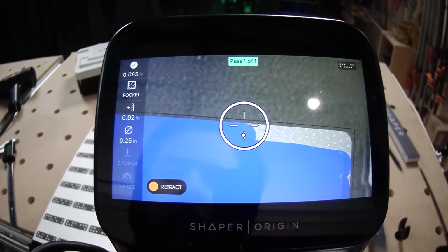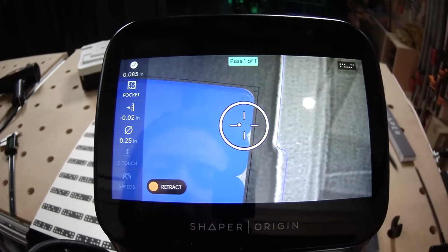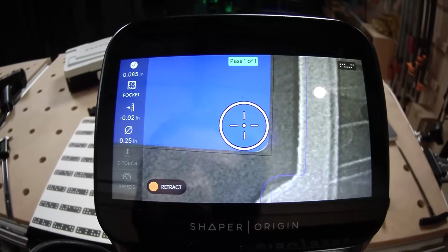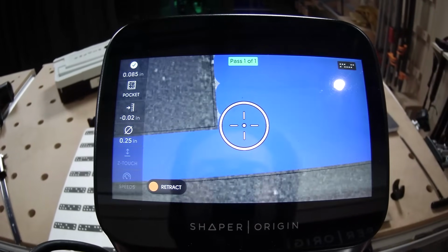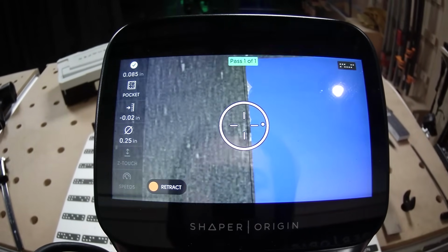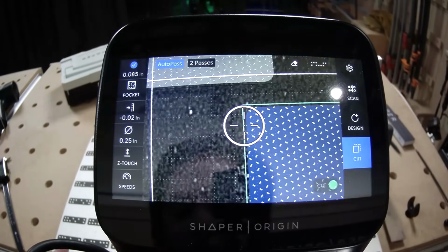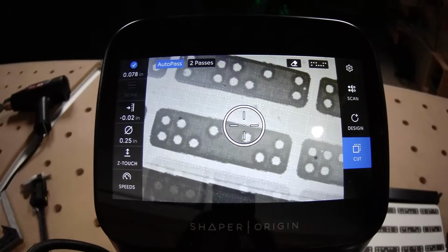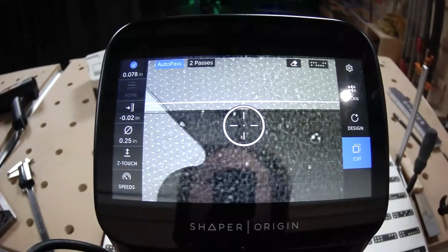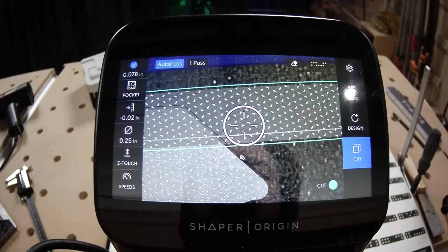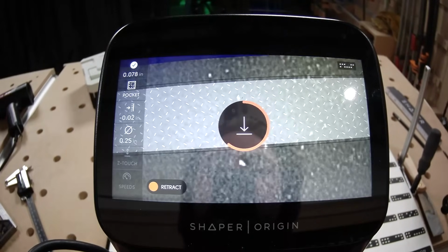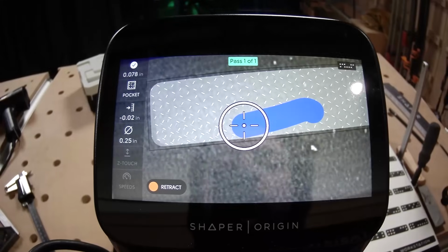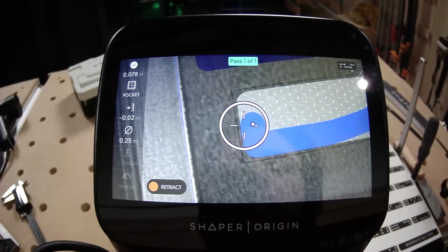That's when you get nasty foam residue stuck to your router bit, which is a negative reinforcement loop there. More stuff stuck to the router bit just creates more and more friction and more heat. And then it just gets worse and worse, frankly. So you want to make sure that you keep moving. If you get in that situation, make sure you keep your bits clean.